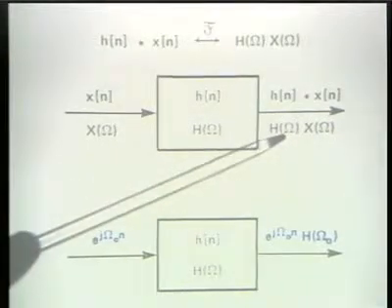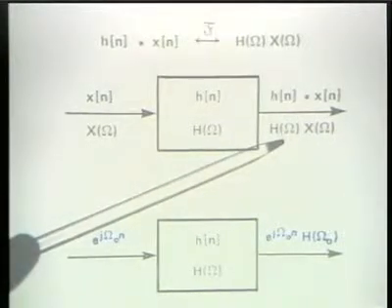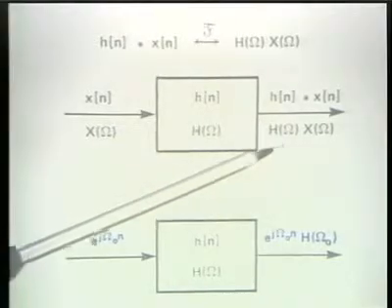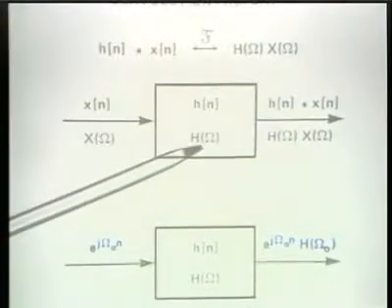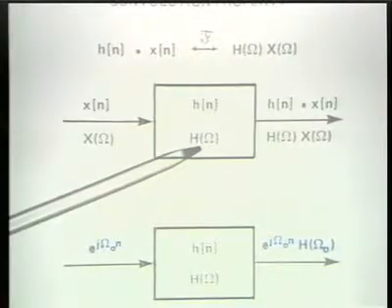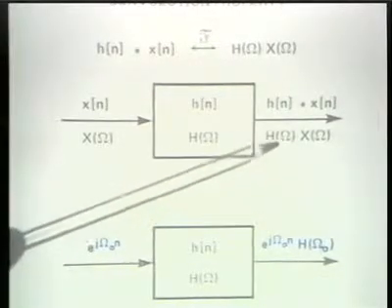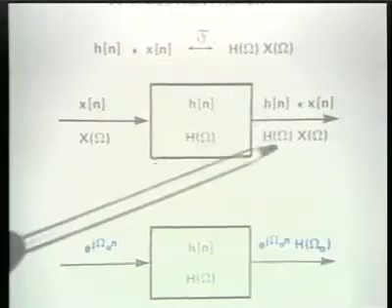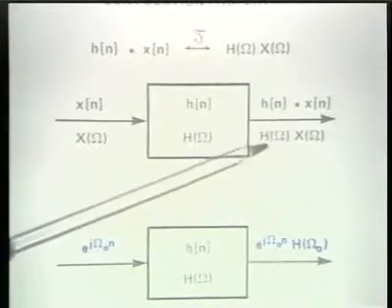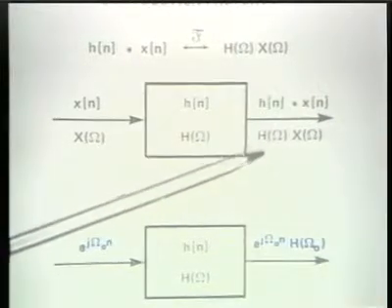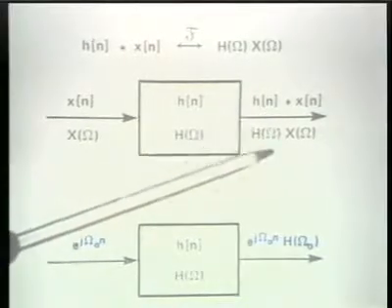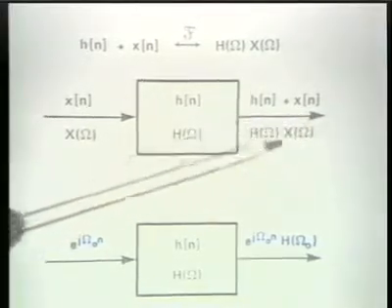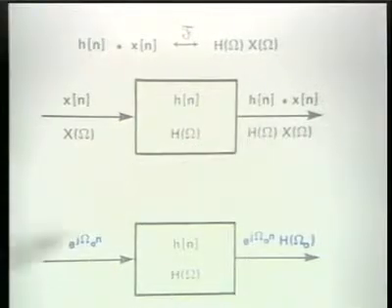So the amplitudes of the output complex exponentials are the amplitudes of the input complex exponentials multiplied by the frequency response. And the Fourier transform of the output, in effect, expresses the summation or integration of the output as a linear combination of all of these exponentials with the appropriate complex amplitudes.